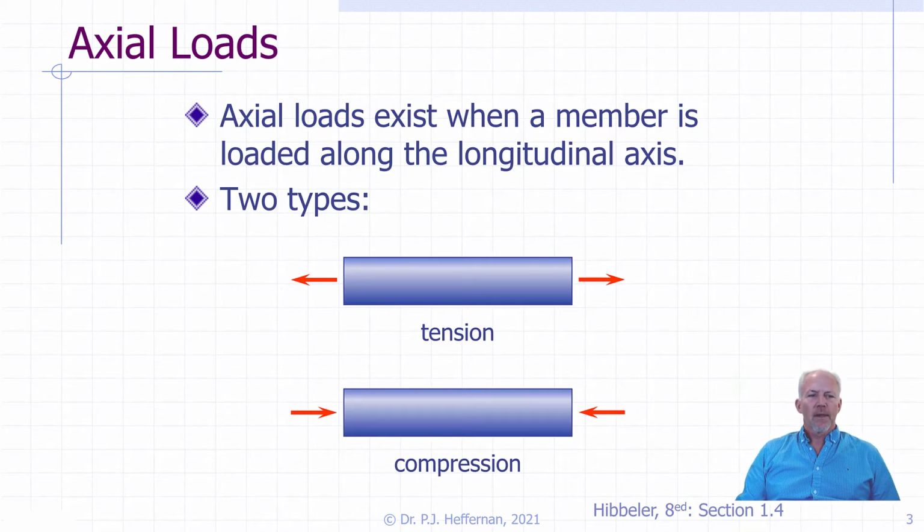of the load. Stresses and displacements will occur in a member when loaded and must be calculated for design or analysis. So you have to ask yourself, what is the difference between analysis and design? Analysis is the determination or calculation of such quantities as stresses, strains, and displacements, when we have known dimensions of materials. Design, on the other hand, is a more difficult task, and it is the determination of the required geometric configurations or characteristics, such as the materials, in order to fulfill all the prescribed functions that the engineer needs. Design and analysis are absolutely interrelated, but they are different.